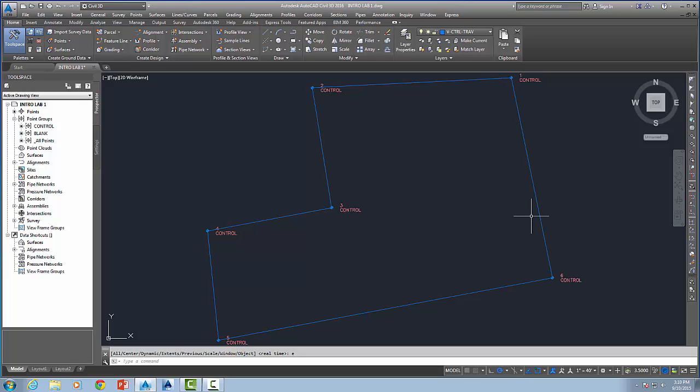So what we're going to do is take a look at a couple of these options and generate points and show you how this will work. If you notice point 11, which is not too far located off of 4, it's kind of over in the northwest corner here. We're going to generate point 11, and we notice that what we have is an angle that is given off of the line 3, 4, and a distance from 4 out to 11.